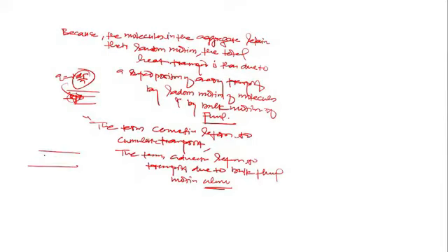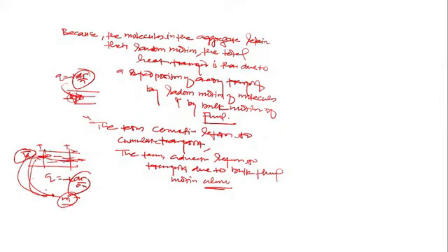Let's say random motion is there and bulk motion is also there. When here temperature T1, here T2, due to random motion the energy is transferred by conduction, given by Fourier's law, minus k dT upon dx. While due to pure bulk motion, the energy transfer is only due to m dot Cp T. Here m dot is the mass flow rate, and mass flow rate involves the bulk motion, because it is density into area into velocity. The fluid is moving with average velocity, and this average velocity is the bulk motion of the fluid. So m dot Cp T1 minus m dot Cp T2 is the energy transfer from 1 to 2.